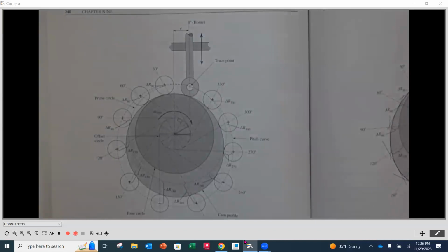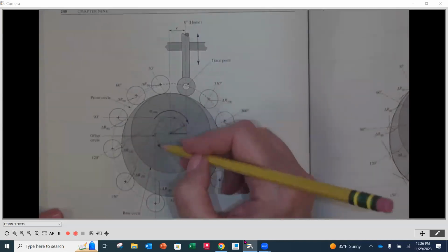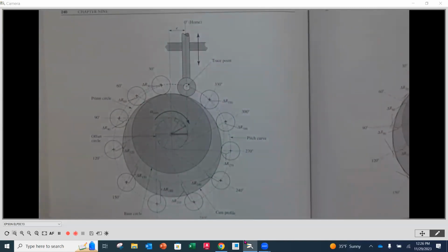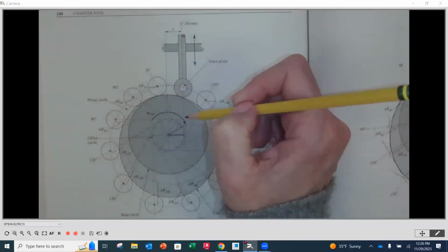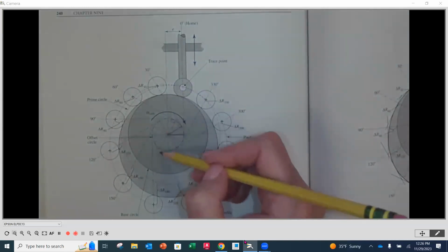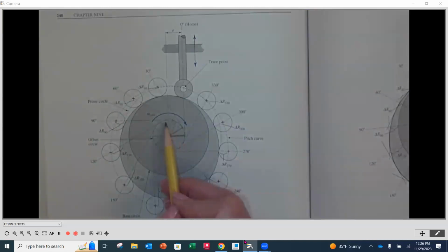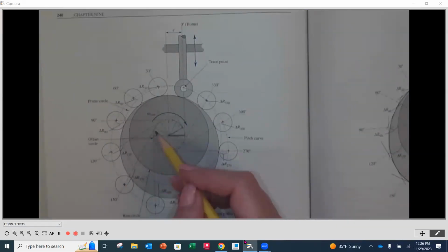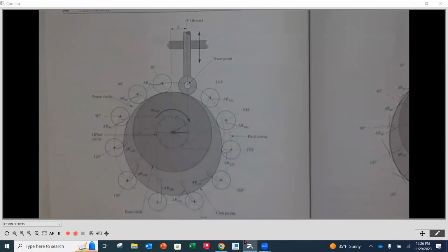These two require laying it out in CAD, right? So you'll have all the information, and once you start constructing these, it'll start to come together. This offset circle is based on the radius of that offset right there. So that's where you're going to start. And then you're going to put each one of these out perpendicular to its corresponding line. So there's a little bit more construction because of the offset.